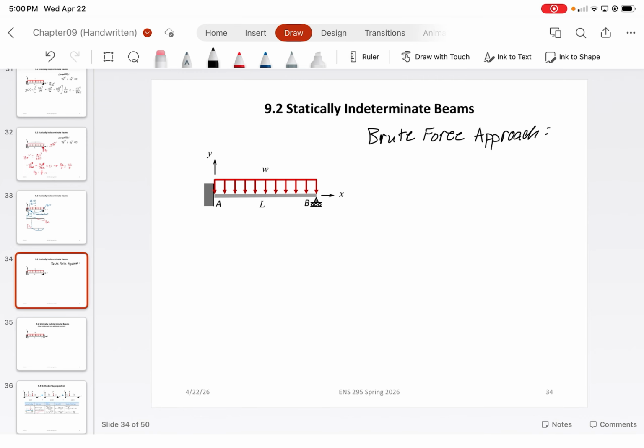For this case, we can write all of our equations just using the deflection equations. We don't need to remove the redundant if you don't want to. You just need to keep in mind the importance of the boundary conditions, how the structure is going to deform, and what the reaction forces are going to look like at certain points. Ultimately that's how you would solve for the unknown constants. So from this problem, we could start off by writing EI d to the fourth y over dx to the fourth is equal to negative w. That's the distributed load, right?